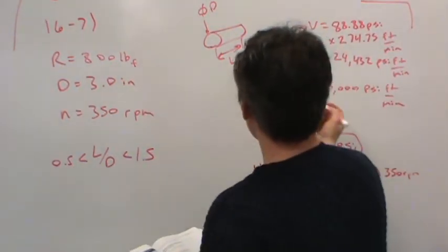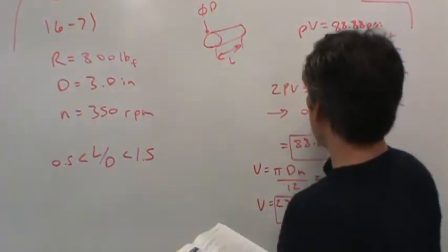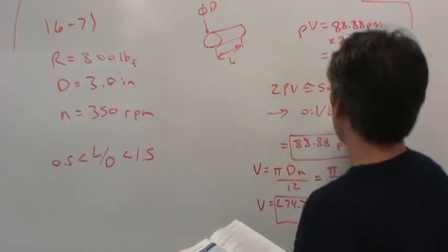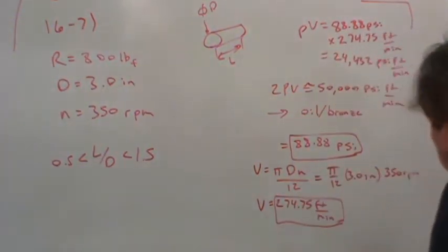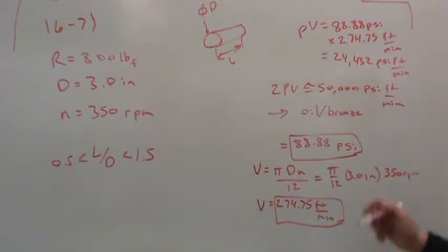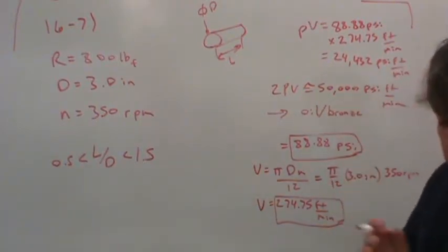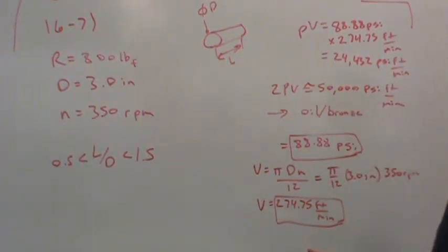And so I'm going to just choose oil impregnated bronze. Basically the rating is exactly 50,000. You could go up from there if you wanted to. You could easily go up to aluminum bronze and it would work fine. It's just probably a more expensive material.